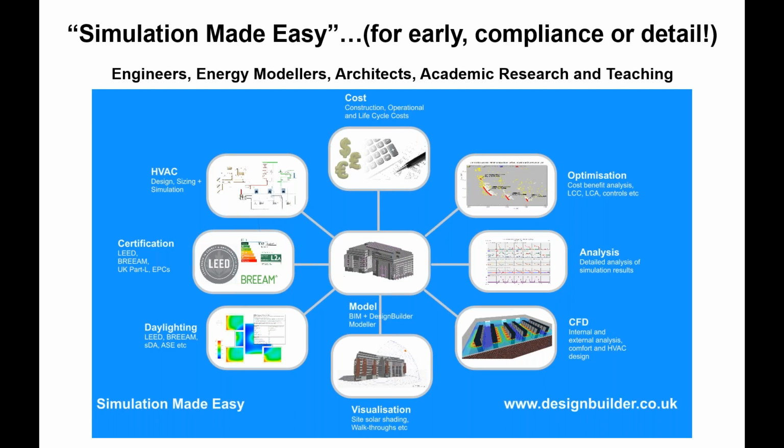So you build that one core model for certification purposes, and then you can do a whole range of other stuff as well. So we can use Energy Plus to do the dynamic energy and comfort simulations, and that enables you to accurately predict or model performance in new and existing buildings, as opposed to the more kind of benchmark NCM type modeling. The latest TM52 and TM59 tools to undertake overheating analysis for Part L, London Plan, BREEAM, BB 101, etc. You can also generate credits for environmental schemes such as LEED and BREEAM.